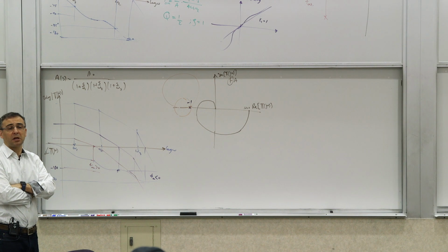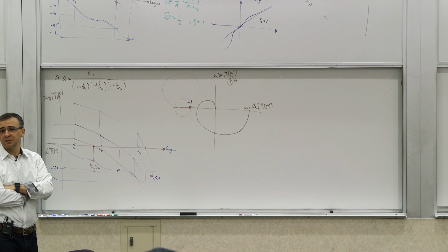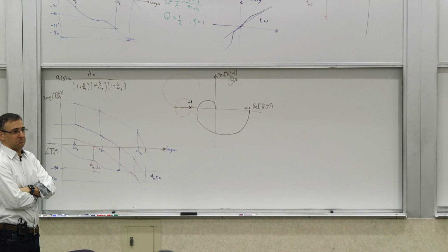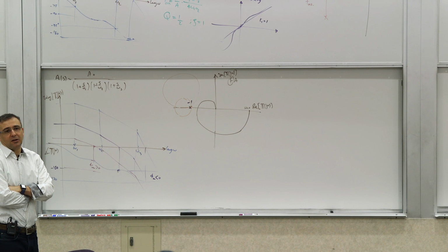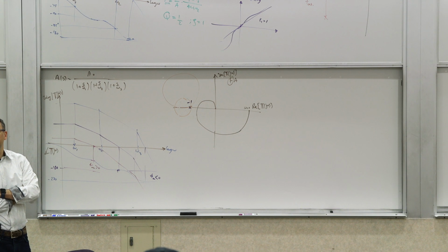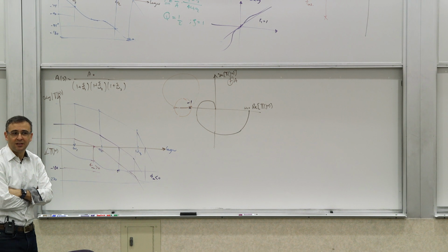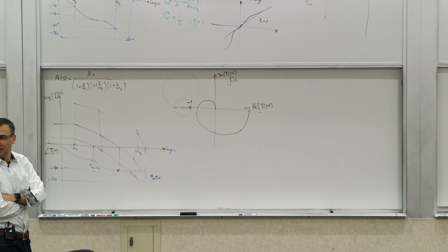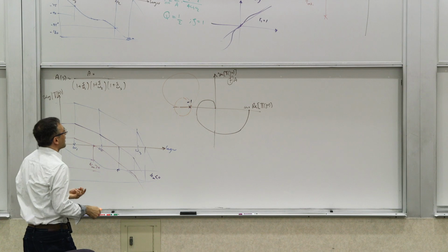But if I have in general a nonlinearity that's first and third quadrant and it's not necessarily monotonic or anything like that, essentially all bets are off, right? It doesn't guarantee that it's unstable, but it can definitely not guarantee that it's stable. So those are the kind of things we need to think about.